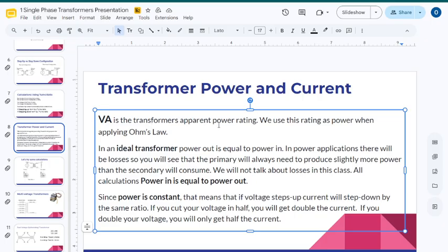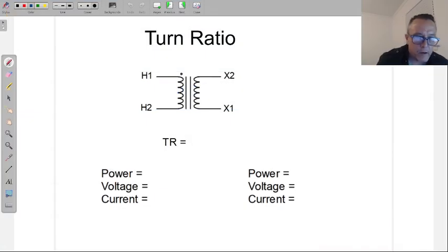All right, this is coming again out of the PDF that I posted. So instead of saying, for example, if you go buy a generator, you're going to buy a kW, watt, system generator. You would buy it rated for a kW. When we're buying transformers, we're buying them to a kVA. That's the one thing on transformers that's different from other components, is they're represented in kVA or in VA. Now VA shows up a lot around the code book.